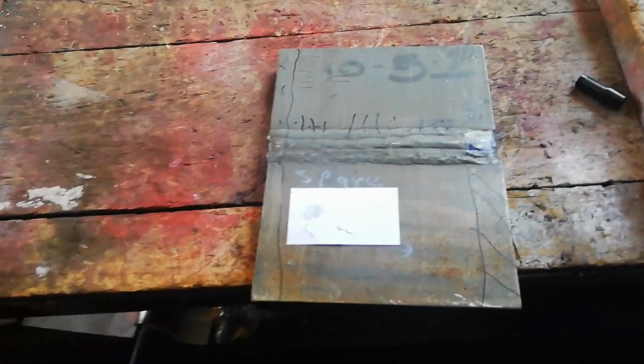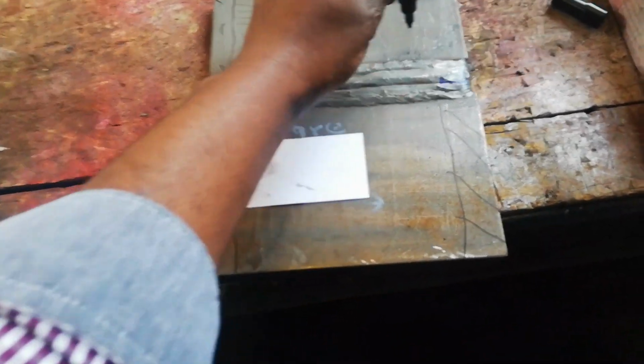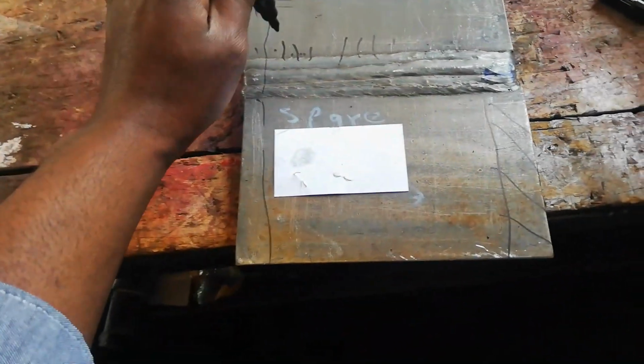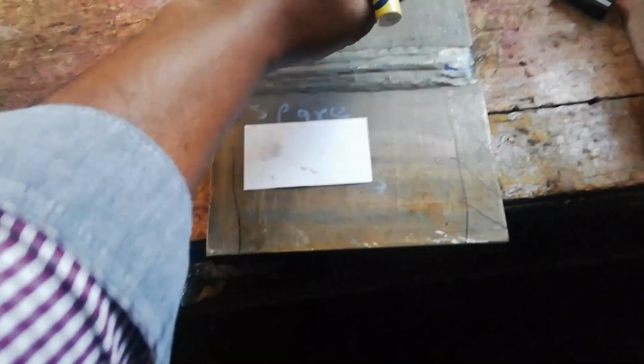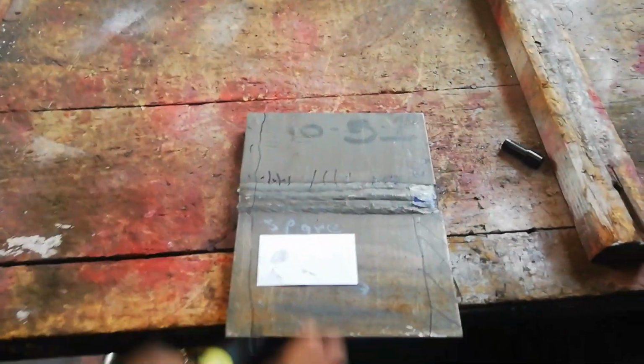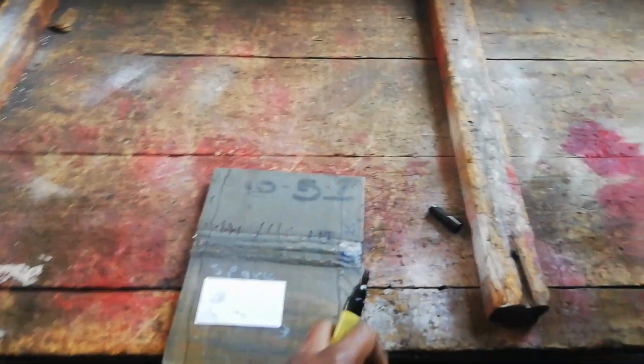So let's say that we are dealing with ASME. With ASME, you're gonna do the same. We're gonna discard more or less 25 millimeter. First tensile, first 2 bends, second tensile, second 2 bends, okay? No impact, no macro, unless the customer wants some, right? So this is eventually how it is done, right?